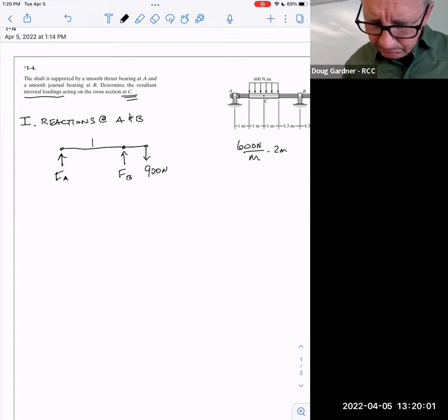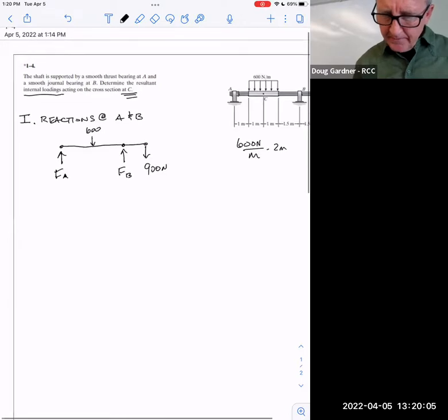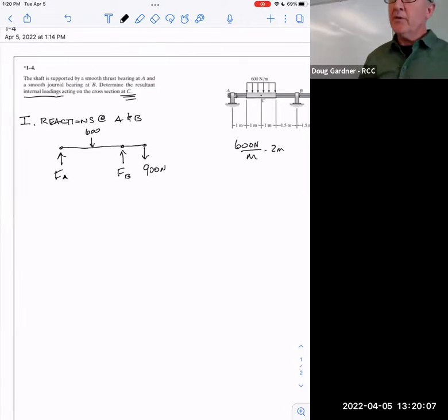So, and also on A, you also have the X direction. That's right. And this is exactly what we ignored all last term. So I should, in a sense, go in here and draw, I'm going to erase this, but I should call this the force of A and Y and the force of A and X. But do you notice there's no other arrows going left and right here? So therefore, the force of A of X is going to be 0.